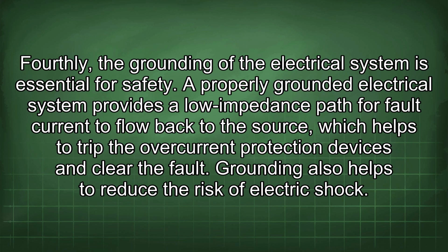Fourthly, the grounding of the electrical system is essential for safety. A properly grounded electrical system provides a low impedance path for fault current to flow back to the source, which helps to trip the overcurrent protection devices and clear the fault. Grounding also helps to reduce the risk of electric shock.